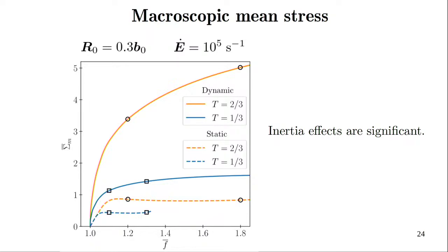What you can see is that the inertia is actually making it difficult for the void to grow. It is even making it difficult to grow in the elastic region. In this case, you can see an elastic slope, whereas here the elastic slope is very steep. That means even in the case of elastic growth, the void growth becomes difficult because of the inertia effect.